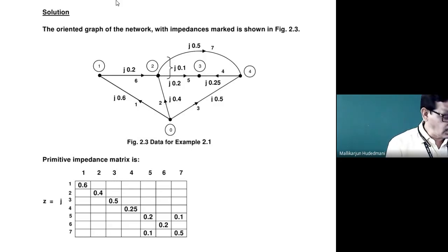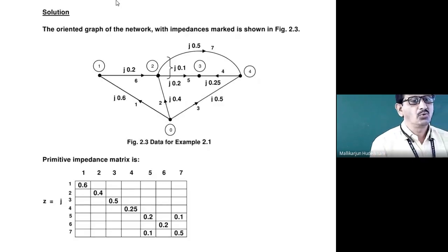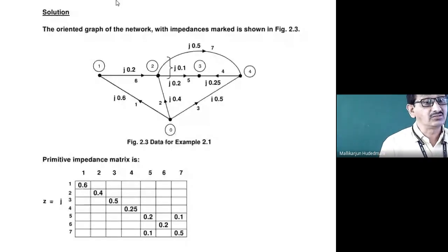So, once I have an impedance notation, this is the way. You may ask me, suppose the entire data is given in admittance form only, and coupling is also given in admittance only. No doubt it becomes Y primitive directly. No need to invert at that time. I have been given the impedance form of representation, hence it is necessary for me to convert to admittance. If the entire data was given in admittance itself, including coupling, no doubt the straight substitution in the matrix positions serves as Y primitive for you.